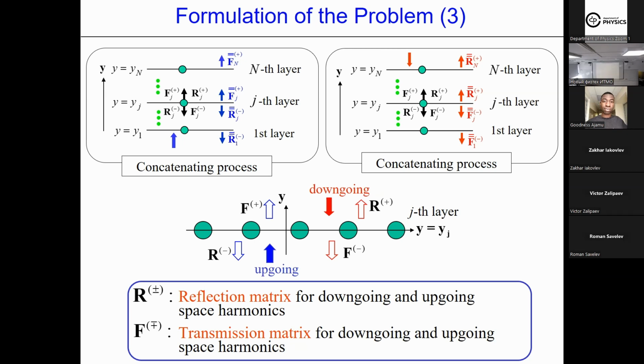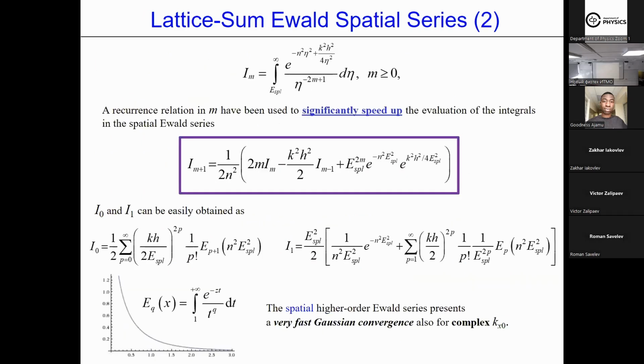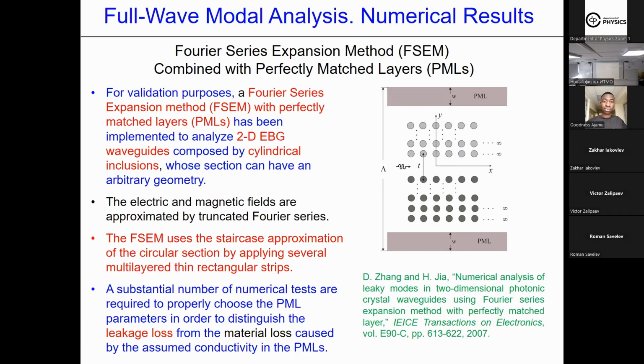Okay. The method which I studied is this series expansion. Here, we can also calculate the complex wave number because we have a PML. But the difficulty here, first of all, is that I spent some weeks in order to understand how the parameters of the PML should be chosen: the thickness and the conductivity of the PML.